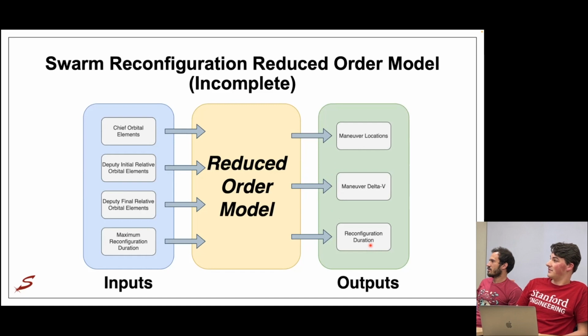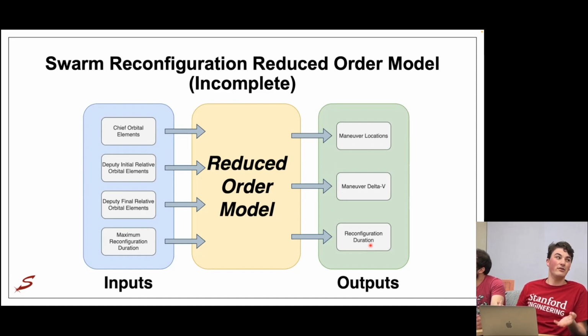The reason it's not finished is because of the problem I've talked about with the delta V lower bound not being reachable. That makes actually computing for an arbitrary pseudostate significantly more challenging in terms of reduced order modeling. Michelle solved that problem for a different set of ROEs and has a nice algorithm that's pretty efficient to essentially do this. It would take a significant amount of work, which I'm working on right now, to go through that full reachable set theory analysis in order to finally arrive at a closed form algorithm that I can guarantee is correct for these new sets of ROEs. So that's where the work is happening right now.